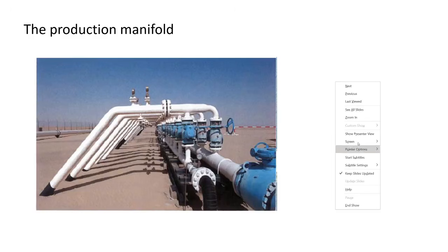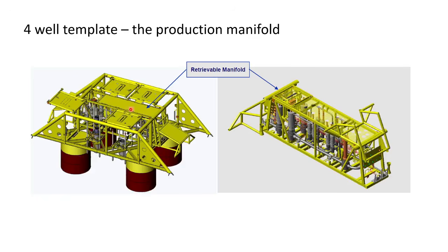This is an onshore field. So see here, these are the lines that come from each well. Yeah, and then they go to two lines. Okay, you see this one is very small, so probably it is used for test. Okay, this won't take the full production of the field. And this one is very big, so this one will be the line for production. And here you have the two routing valves. Okay, the routing valve to send the production of well 1 to production or to send it to the test. Okay, you have many wells here. I think this field is in Libya.